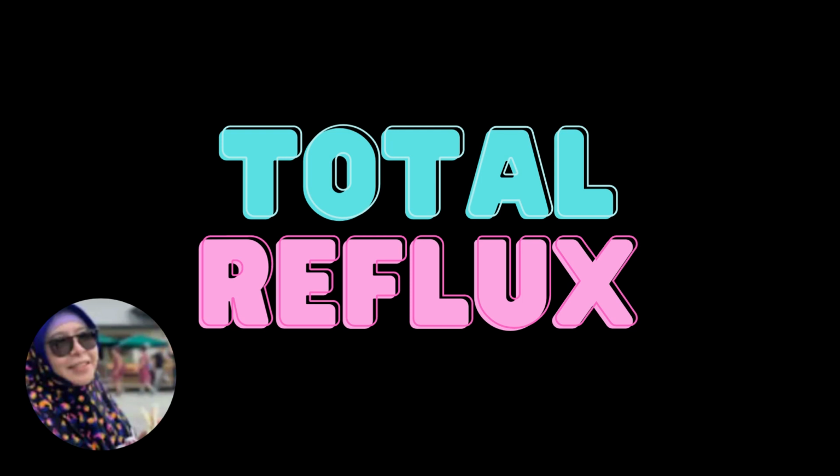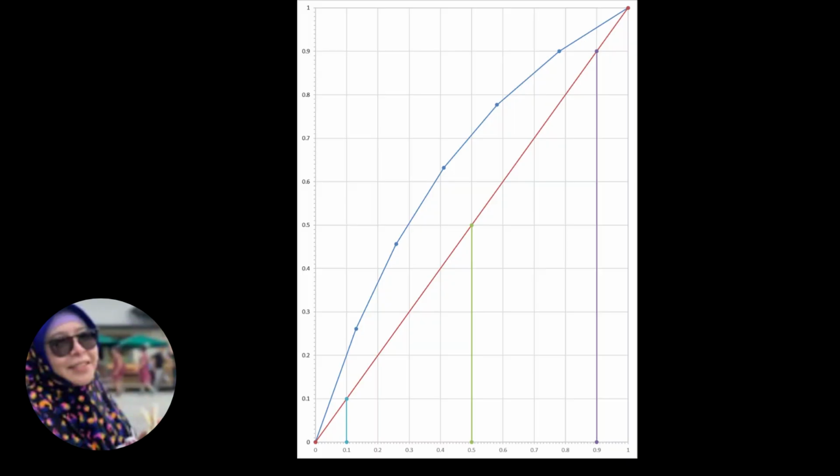For total reflux, the information that you need is the mole fraction of the more volatile component at the bottom product, the mole fraction of the more volatile component in your distillate, the 45-degree line, and the equilibrium curve. Using these four pieces of information, you can draw the stages.